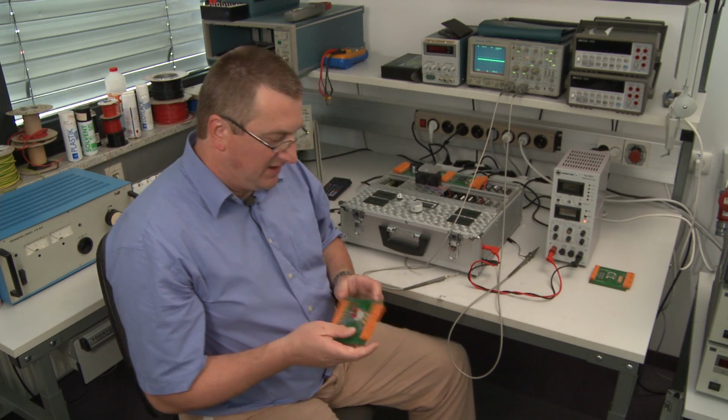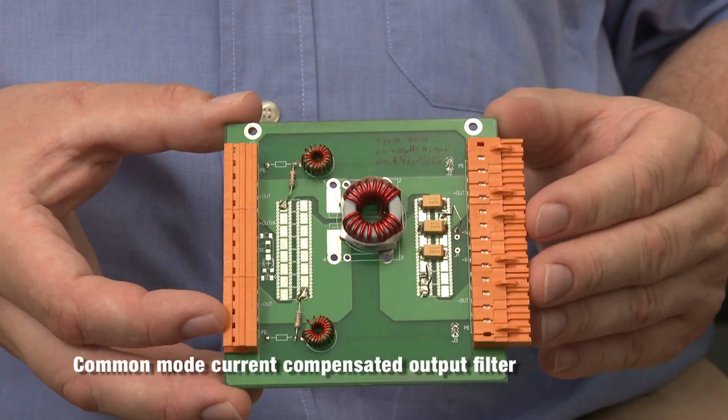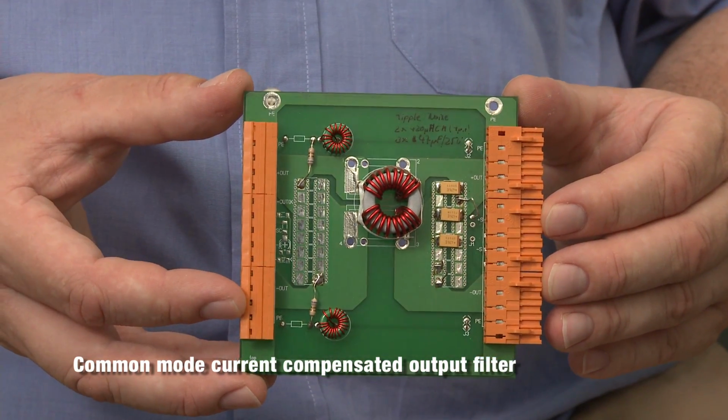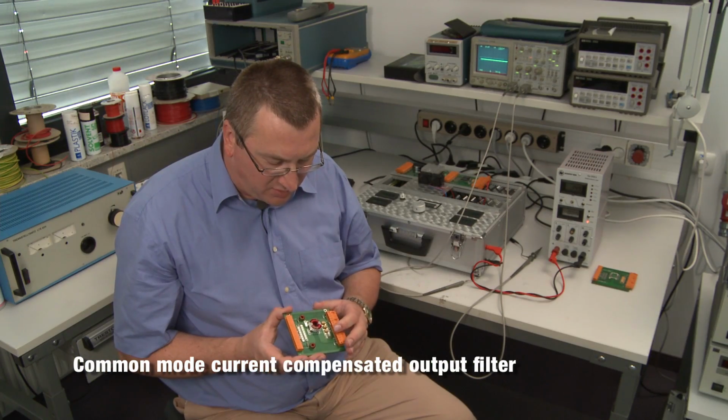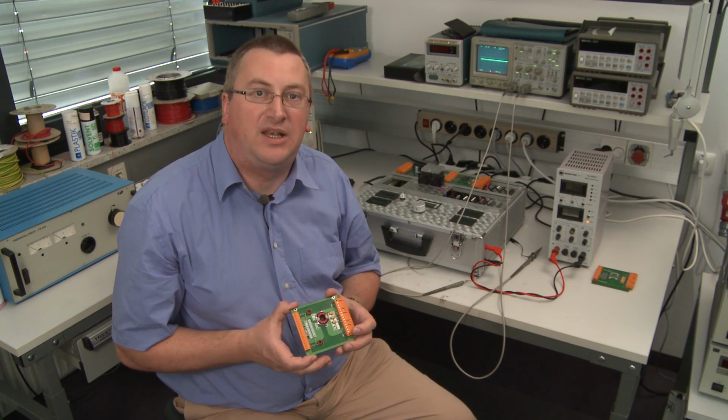For special applications where I really need a very low output ripple noise, we can also add not only a differential noise filter but also a common mode noise filter. In this case I will use a common mode current compensated output filter that is also compensated for regulator stability.